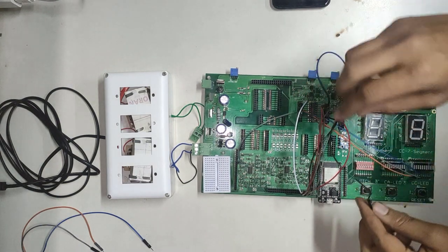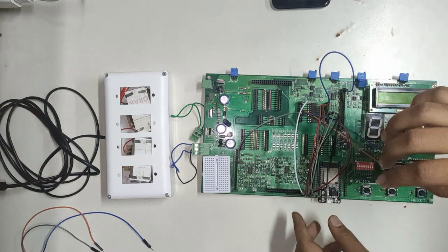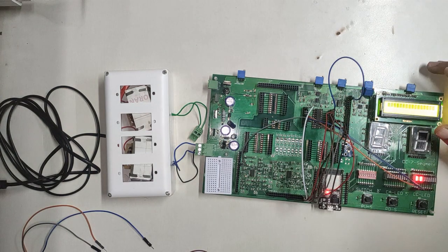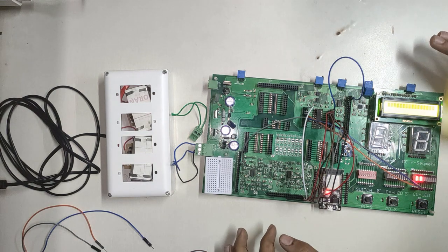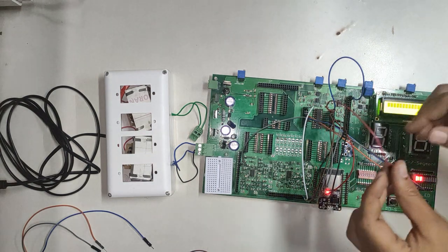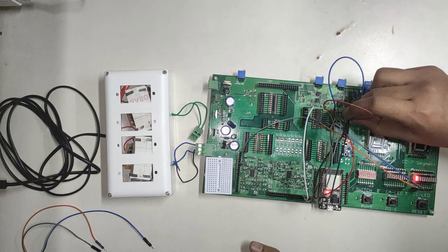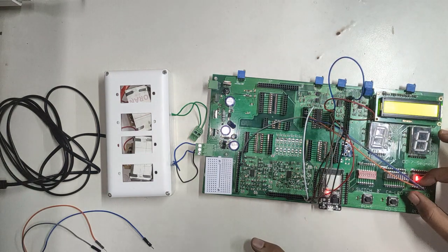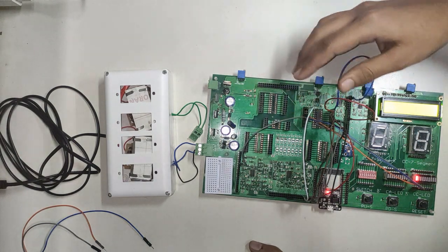So here you have completed all the connections for the 4-bit comparator. After making the connections, this is our circuit. Now let us verify the truth table. We are considering the first case on the truth table, which is A3 greater than B3. Our red wire is A3 and B3 is the white wire. As A3 is greater, A3 must be logic 1 and B3 must be logic 0. In that condition our orange wire is 1, which is pin number 5, which is OA greater than B.